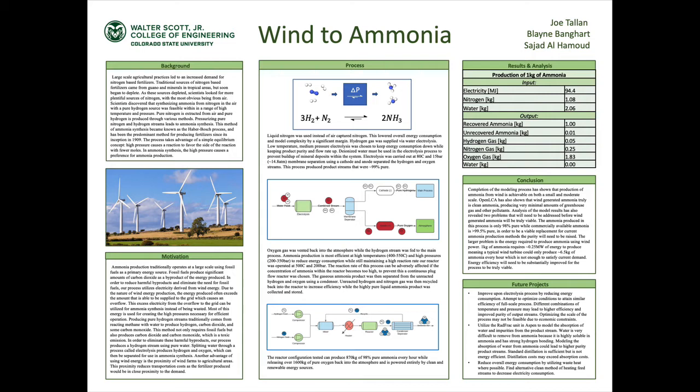So overall, we had two reactants, which were our pure water, or our deionized water, as well as our nitrogen feed, which we purchased instead of capturing from the atmosphere. And we had two products, which were our pure ammonia stream, and our purity was about 98%, which is slightly under the commercially viable range of purity, but we produced about 870 kilograms per hour of ammonia. And our second product was our oxygen, which we produced at about 1,600 kilograms per hour, and this was vented straight into the atmosphere.